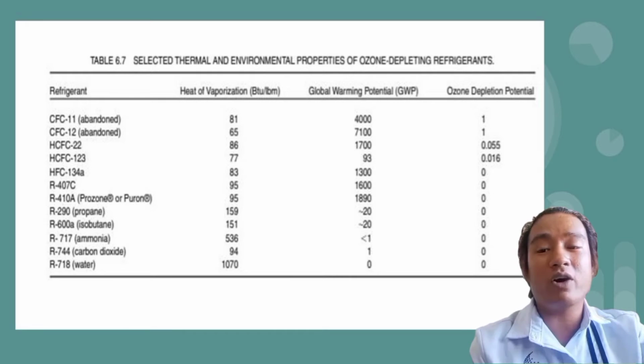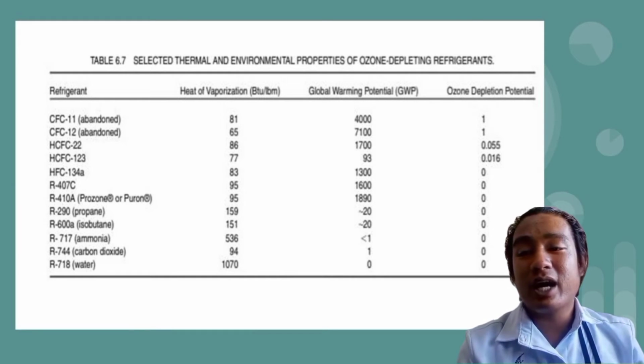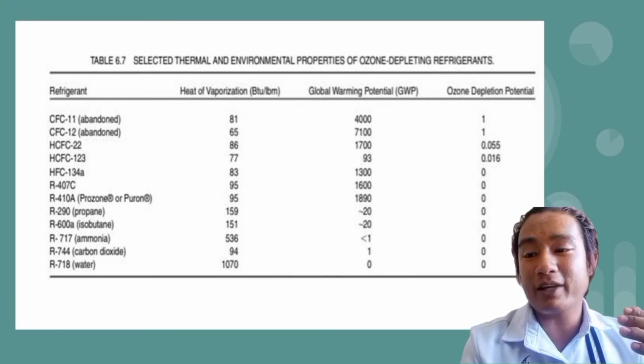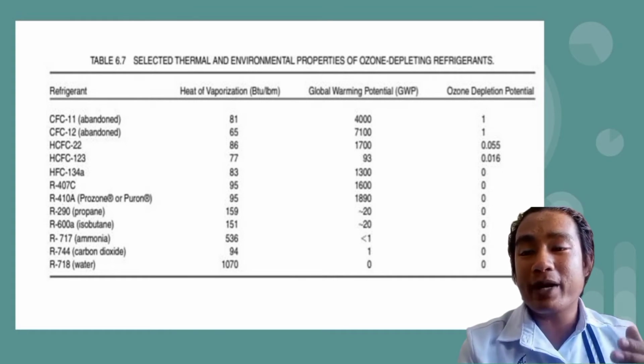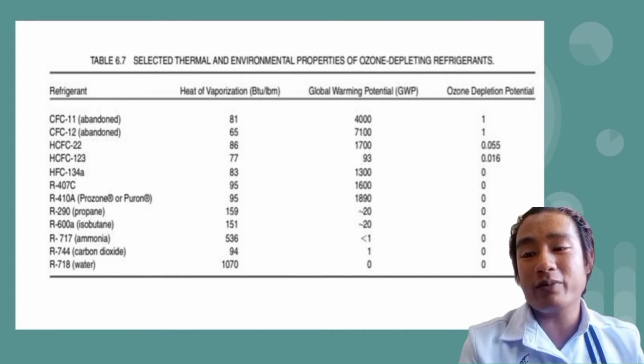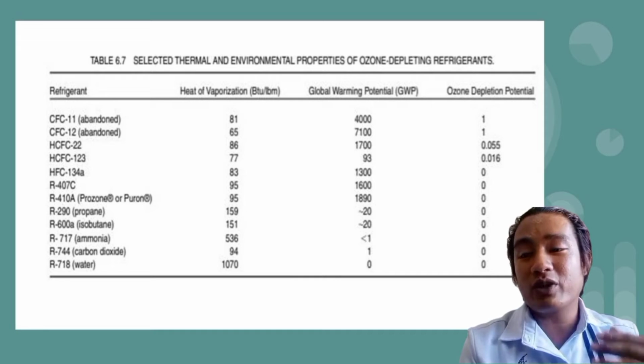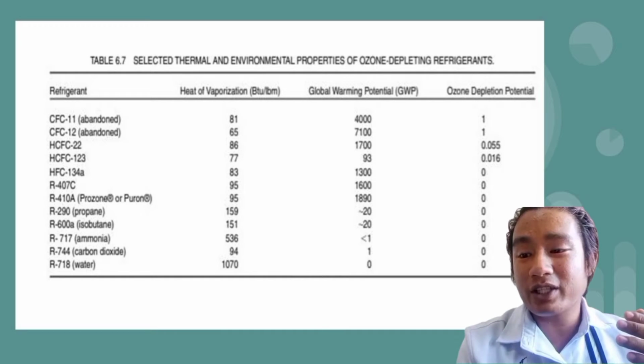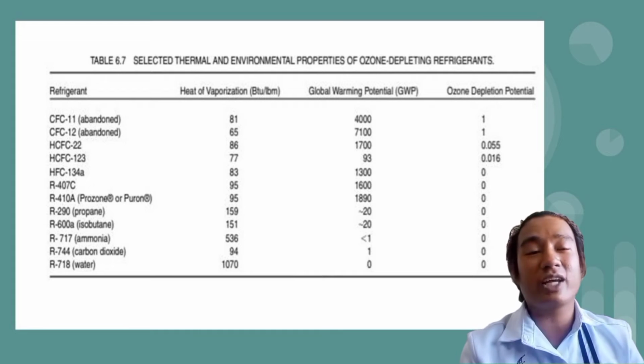Ammonia is a good example of a low-cost refrigerant which has good heat transfer properties and thus good efficiency. It has been used extensively for industrial refrigeration applications and is being developed for commercial air conditioning, mainly in Europe. Ammonia is highly corrosive, and instead of the copper-based alloy used in conventional air conditioning systems, more expensive stainless steel tubing or aluminum is needed. Ammonia is moderately flammable and toxic, so it is hazardous to our health. Ammonia systems must use open drive compressors, which result in some refrigerant leakage. Because of safety and reliability issues, ammonia is not being considered seriously for air conditioning applications in the United States. So in the United States, it is already banned and not considered to be safe.